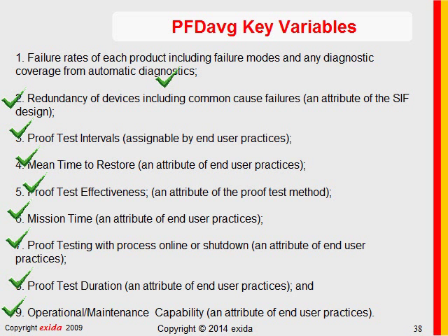Exida does estimate proof test coverage as a function of example proof test methods. And if you are using one or more of those proof test methods, we recommend you use the proof test coverage given by that method.